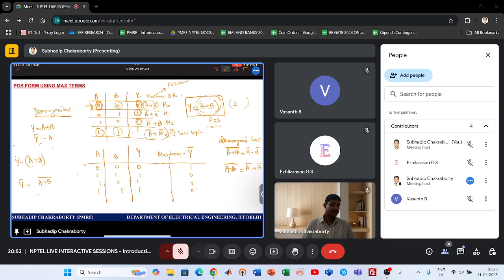So when you break the not sign among the variables, this sign gets inverted with the dot sign. Similarly, here was a dot sign. When you broke the line, the dot got replaced by plus. So to break the long line, replace plus with dot or vice versa. Now dot represents AND operation and plus represents OR operation.